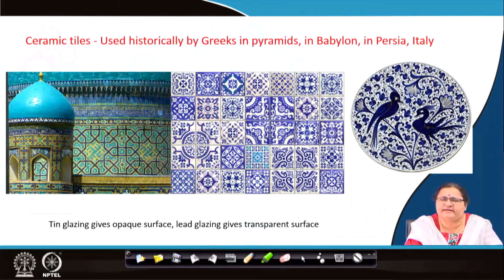If you remember, when we studied terracotta, either ground glass was mixed with the clay, or else glass was put in the furnace. So, glass actually was fumed and the fumes were getting coated on top of the terracotta, giving it a kind of impervious coating. If you remember the term impervious, water absorption will be minimal, so its long life will be assured.